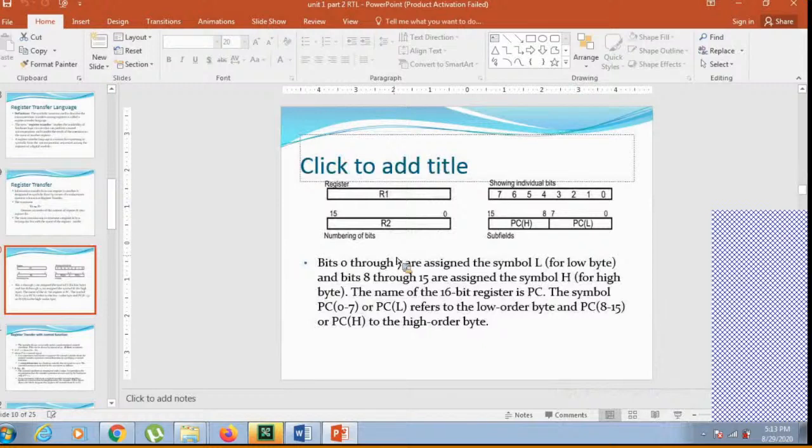Load input will be activated, and in the immediate next clock cycle, at T plus 1, the transfer will occur. Immediately once this transfer is done, the load input will become 0, or it will be deactivated. Why? Because if load input stays high, meaning the value of P is equal to 1, then register transfer will happen throughout all the clock cycles. But that should not be there.